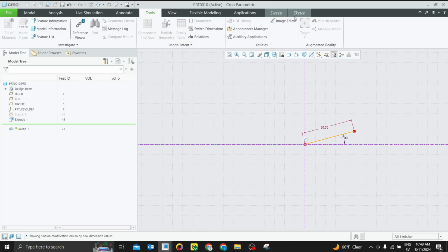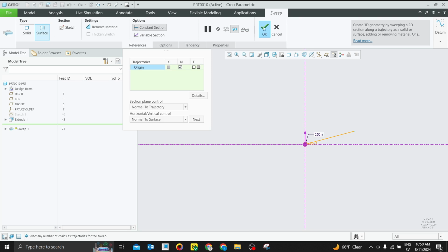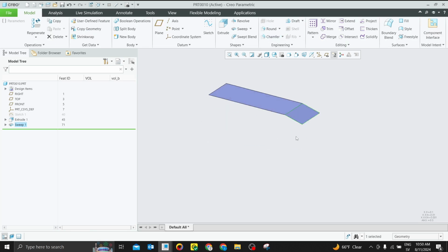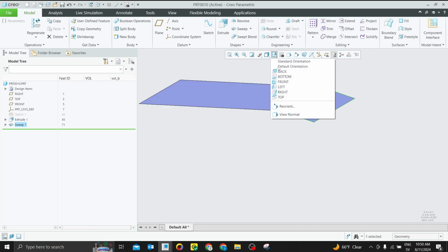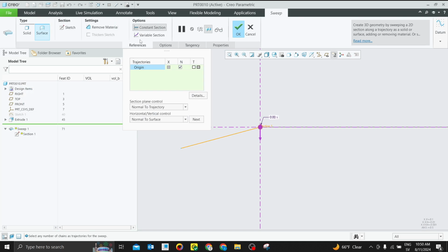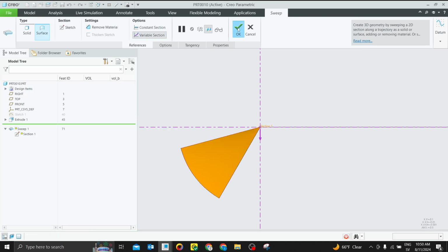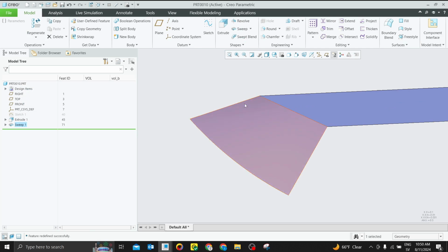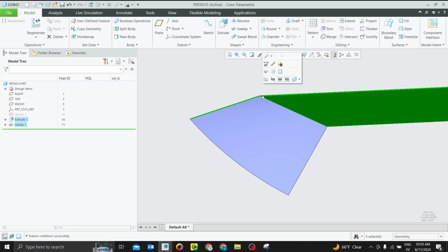Now if I go back to my sketch, you can see my profile surface is having a constant angle. Let me go back here to illustrate why. We have to select variable here for my profile to vary. You can see we said start from 45 to 15. Therefore, the angle between these two edges at this point is 45, but these two here is 15.